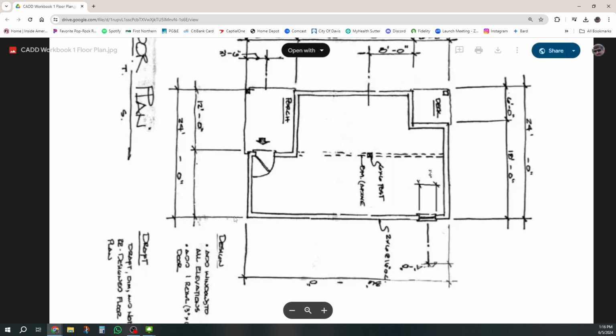5.5 inches. If I draw this all the way around and offset it 5.5 inches, I'll have my shape. And if I draw this little post, it looks like it lines up so the edge of the post is even with this inside core. So if I put it there and then moved it 8 feet, so the center was 8 feet from here, that would be good. So that's what we want to draw.